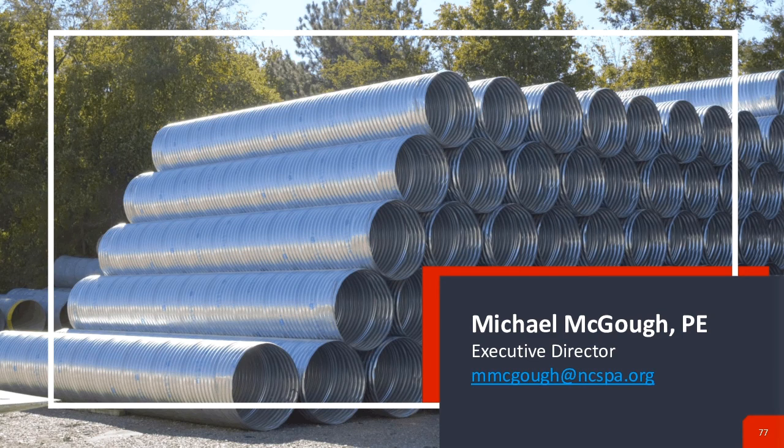Yu Chen asked, do people use HDPE or other types of plastic pipe for detention? Sure, Yu Chen, they can, but we recommend that you use corrugated steel pipe for your detention and retention needs. Thank you, Daryl. Well, gang, if there's nothing further, we got 2:58. I see Daryl's typing something else here in the chat room. We can give him another minute or two. Yeah, diameters for HDPE are more limited. Certainly up to 60-inch, where we can go up to 144-inch. Very good point, Daryl. Thank you for that.